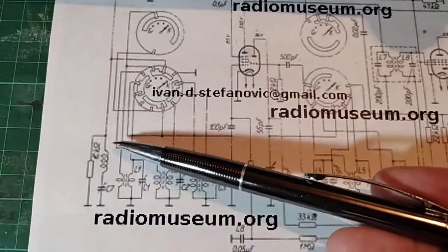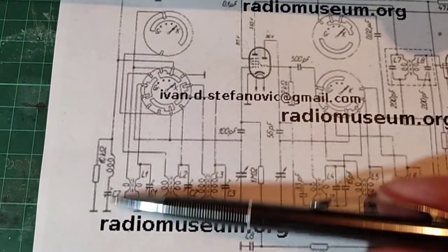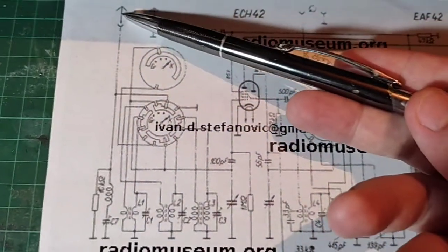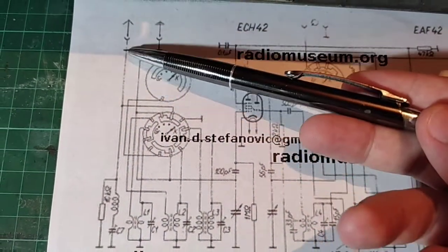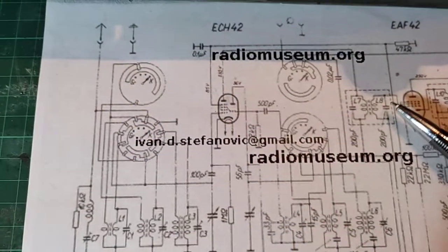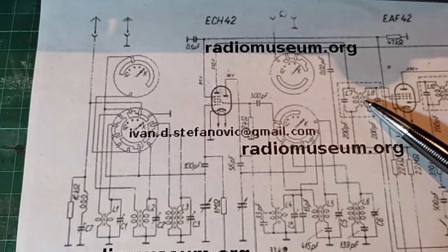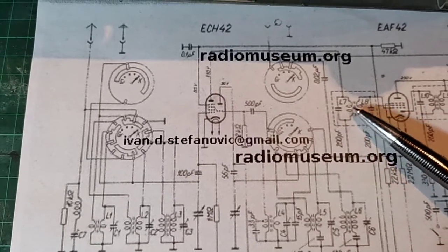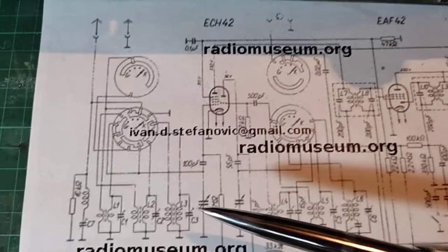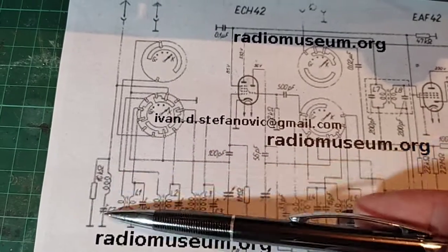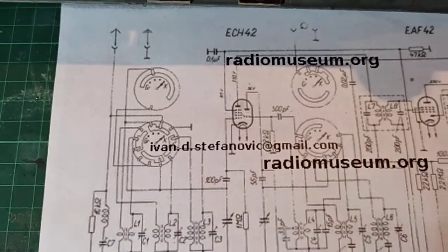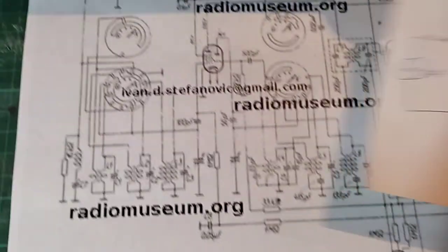And the reason for this coil and oscillating circuit here to exist is to ground any signal that would come at the exact frequency of the intermediate transformer, because that could cause some interference and so on. So the goal now is to determine at what frequency this circuit resonates. It's actually a simple thing to do.